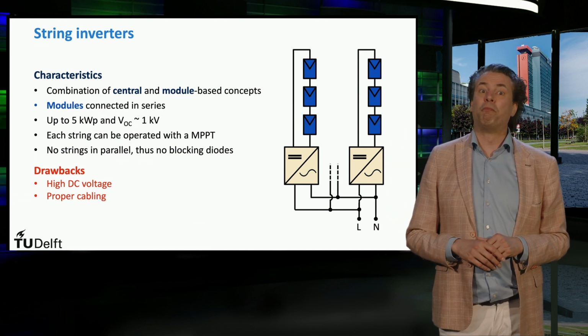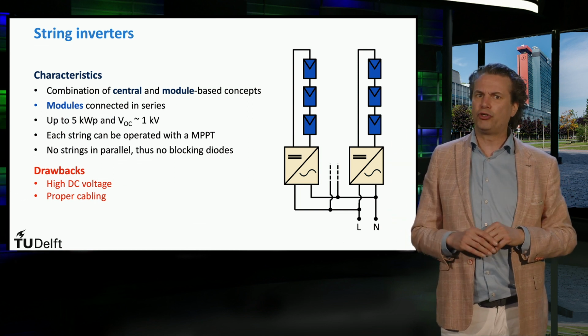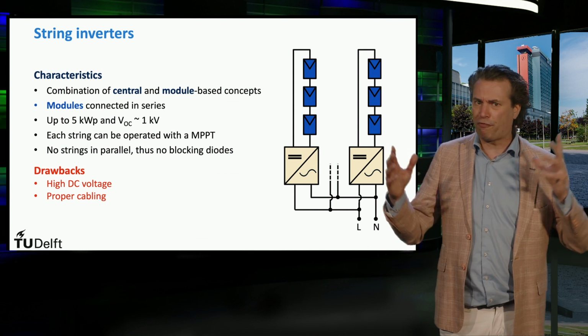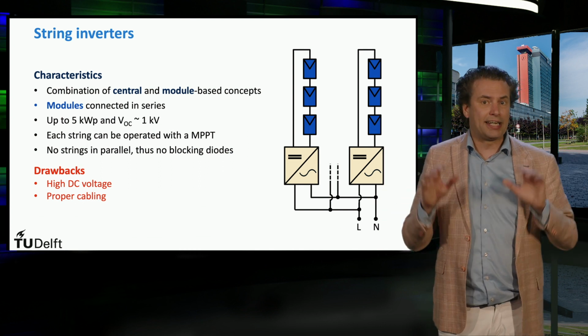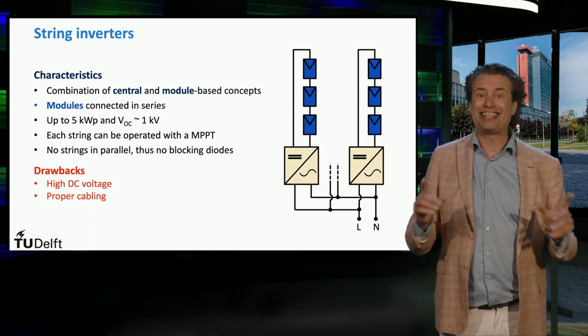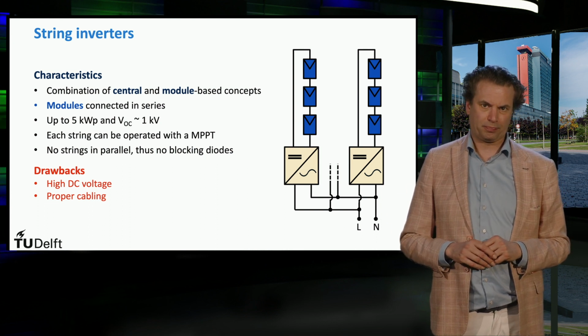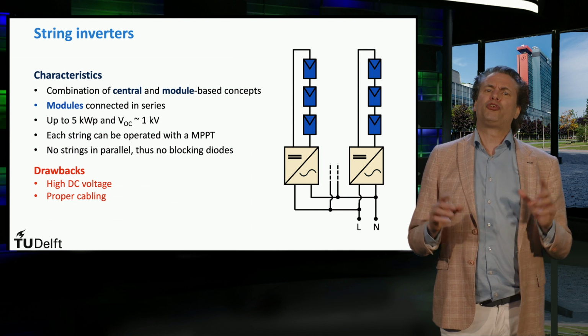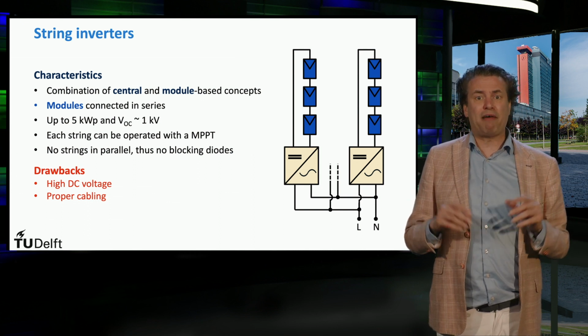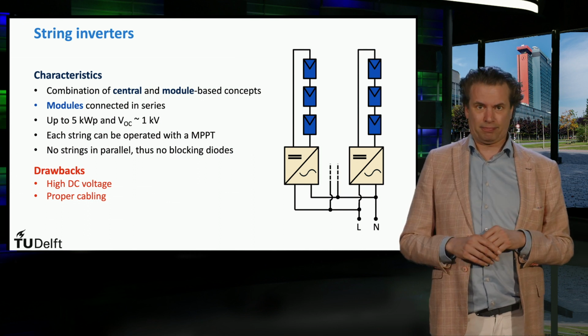Here this issue is even more important because string inverters are usually installed in households or in office buildings without designated support structures or increased safety requirements. The protection of the system also requires special consideration with emphasis on proper DC cabling.